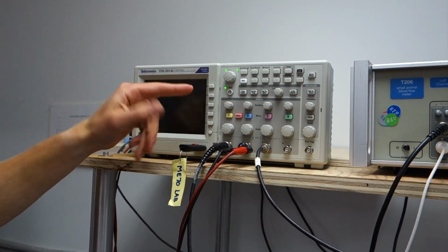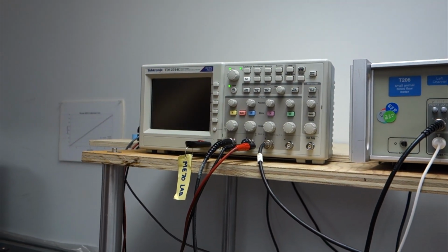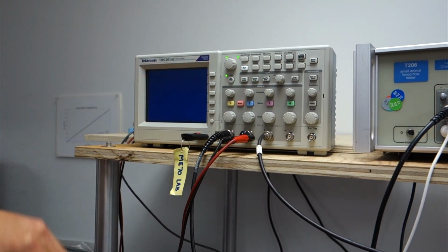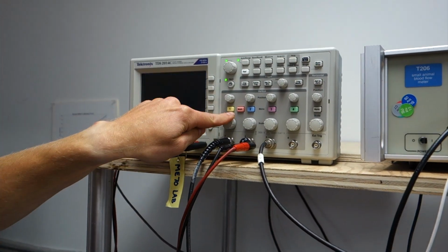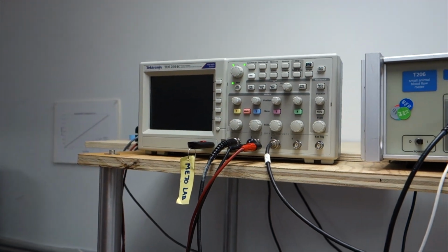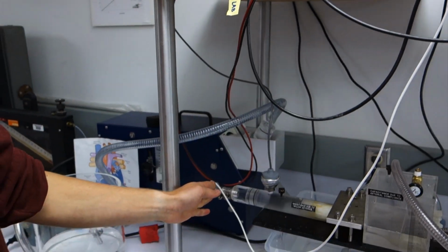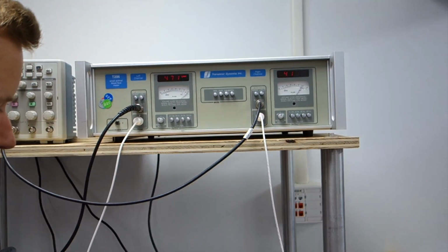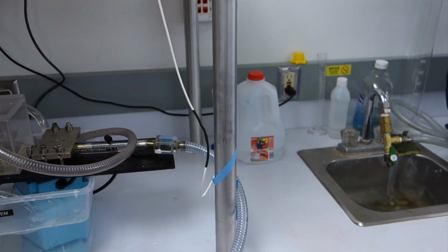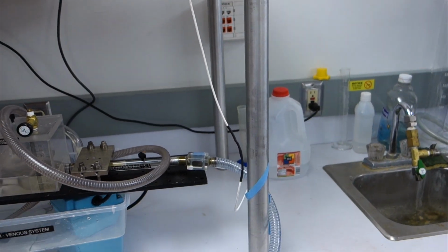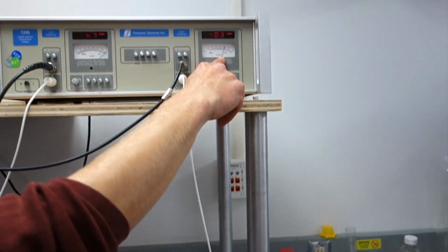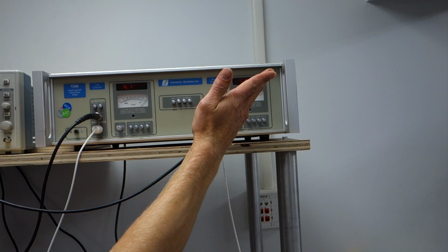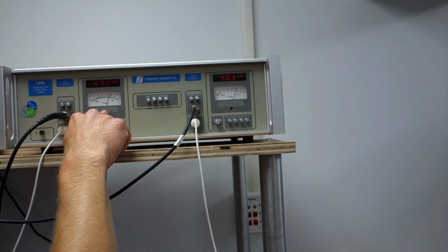So Q1 will correspond to channel 1 on the scope, and this is important for you to look at because you're going to be trying to relate channels to flows and pressures in a second here. So Q1 is channel 1. It's also the furthest left in the setup. And then Q3, if you work your way over here, is pretty steady. You should see that the needle here is fairly steady. There's still some oscillations, but it's pretty much stuck at a constant rate compared to Q1.